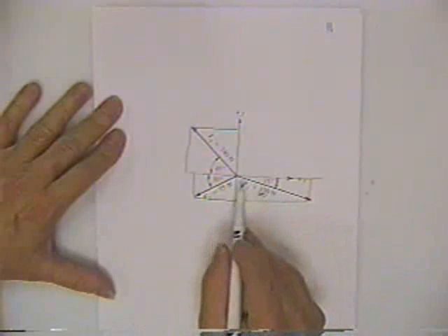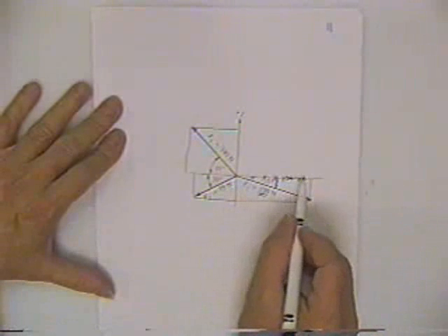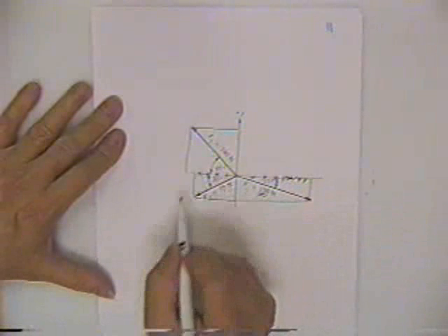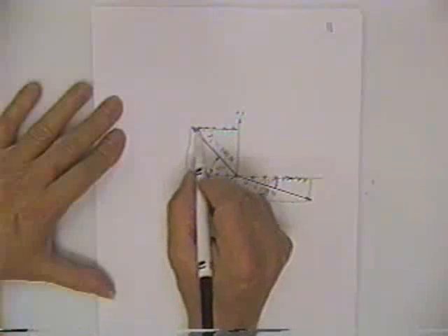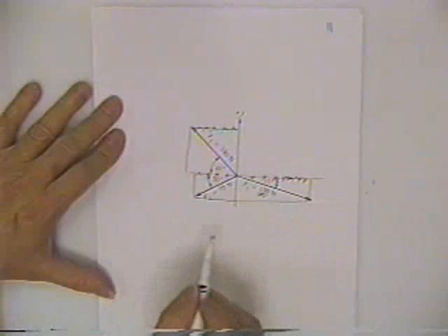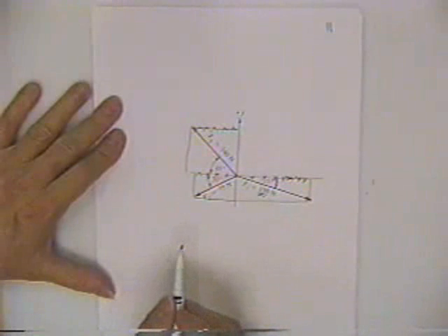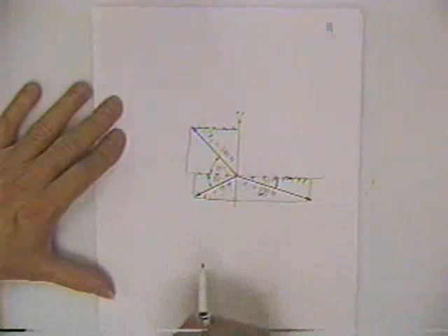You'll then be able to add this particular horizontal force, subtract this horizontal component, subtract this horizontal component, and the resulting sum of those three numbers would be the total horizontal projection of one single resultant for these three forces.